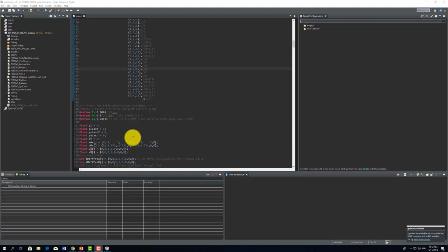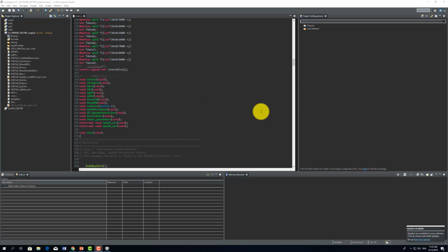To define more of the components of our voltage vector operations, of course, we have to define the sampling time, which we include here as 0.0001, or that's simply equal to 100 microseconds. And of course, we have here the stator resistance and the inductance value. We have also included in the main C file the different prototype functions that we need to run the program.